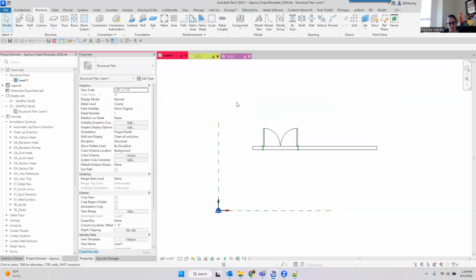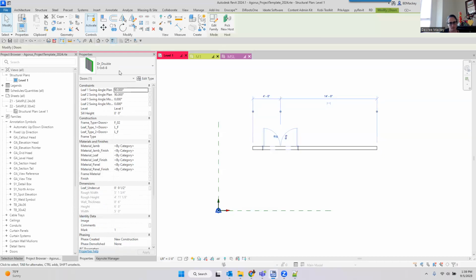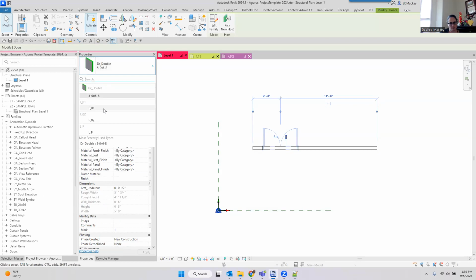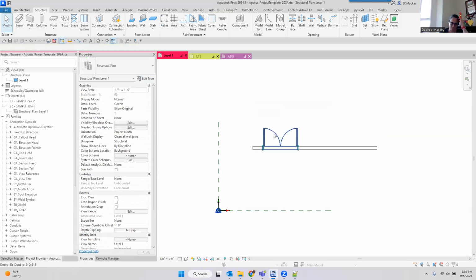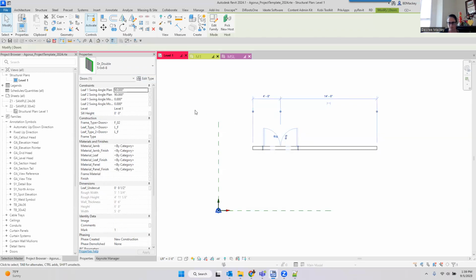There are a few things that I've learned that I have added shared parameters for. If I were to switch this from one door family to another door family, and I wanted it to maintain values, like I never really figured I was ever going to schedule my swing angle on a door. When I originally started my doors way back 18 years ago, none of these were shared parameters. But then when I switched it from one door type to another door type, my angles went back to the default of 90 or whatever the default for that family was.